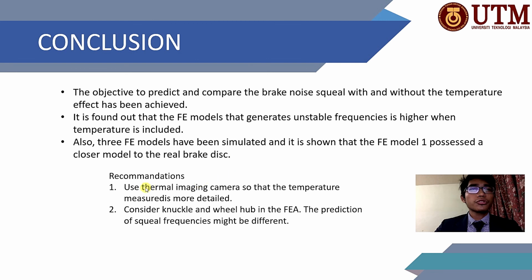So for the future work, maybe consider using thermal imaging cameras so that the temperature measurement is more detailed, and also consider the knuckle and wheel hub in the FEA of the component. The prediction of the squeal frequency might be different.